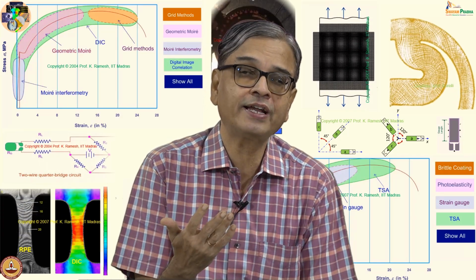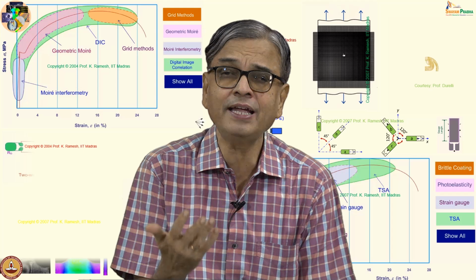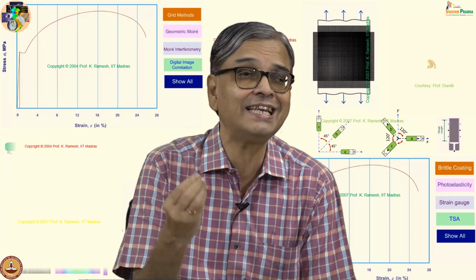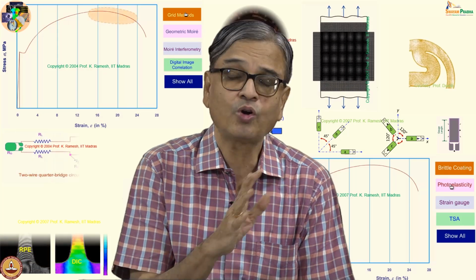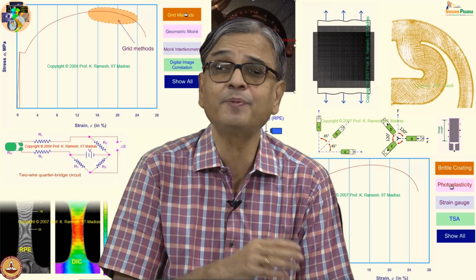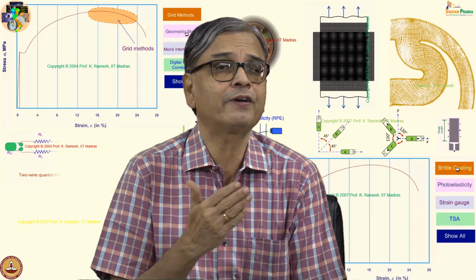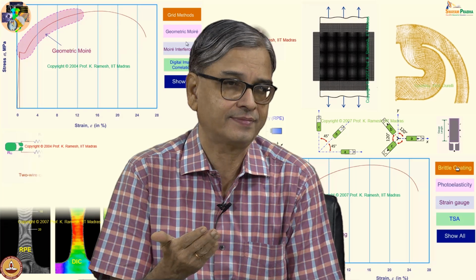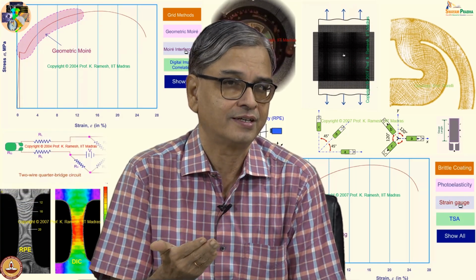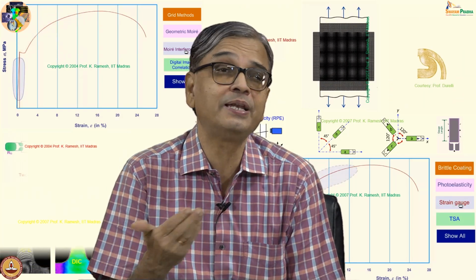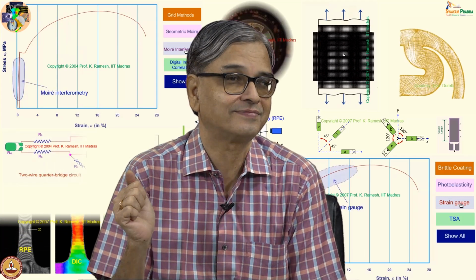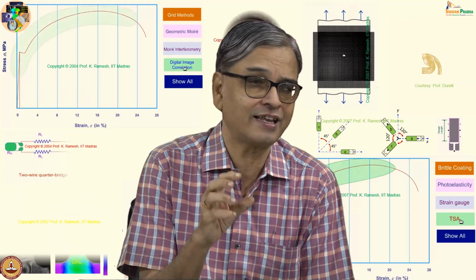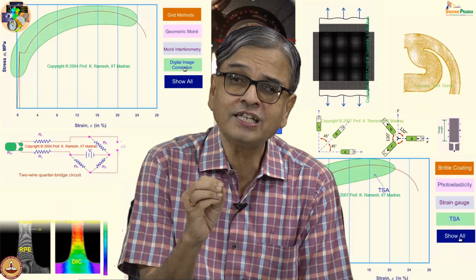What is the other way of doing it? You know, resistance is rho L by A. So the other way of doing it is reduce the cross section to the least possible. With all those calculations, people have found, even if I want to have 100 ohms as the base resistance, I need about 100 millimeter length of the wire to do it. Because if I have higher and higher resistances, any small change I can make the measurement.